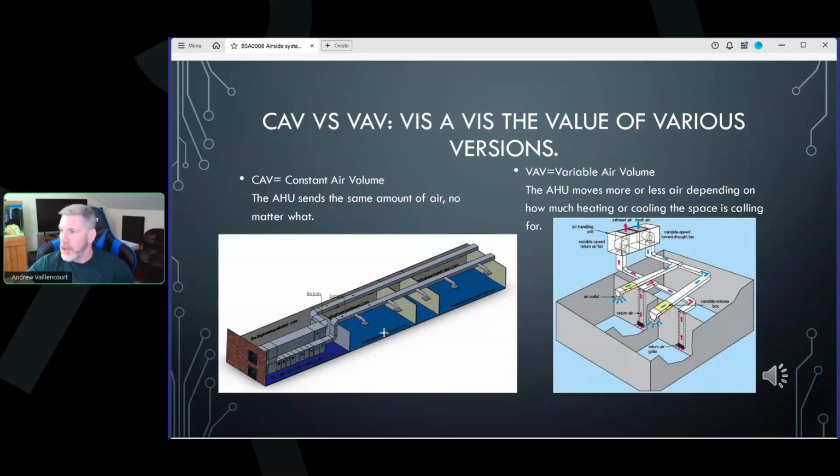And that's what you see on the left here. Here's your air handler. One supply pulls air from the space. Here's your return. It does whatever it's going to do. Maybe it exchanges with some outside air. Maybe it doesn't. And then it sends it right back out to the space. These are what they call discharge grills or registers. If you want to sound really nerdy, these are the registers.